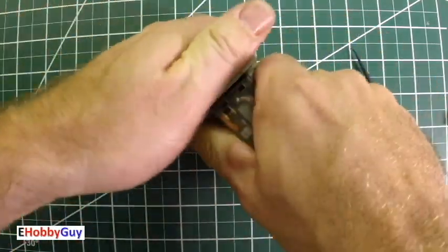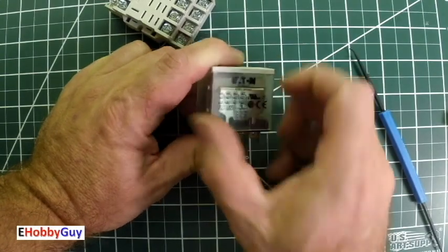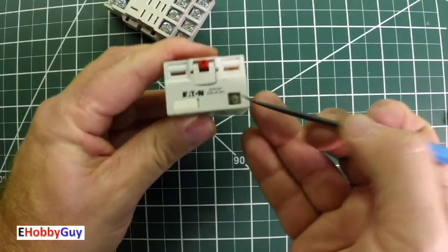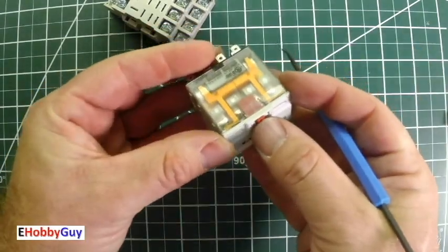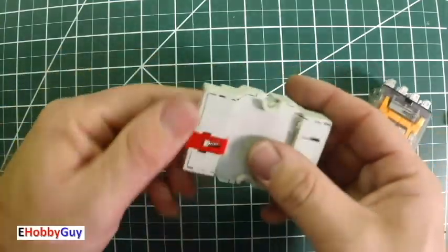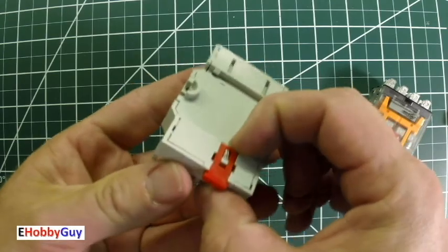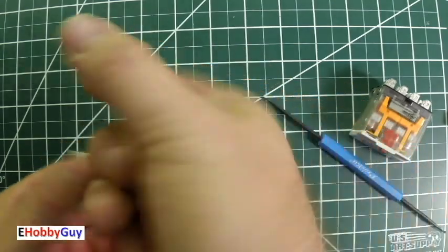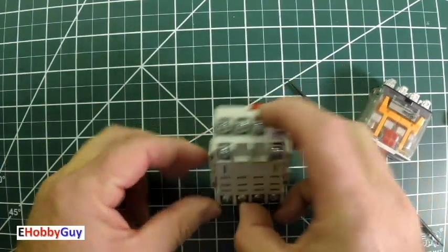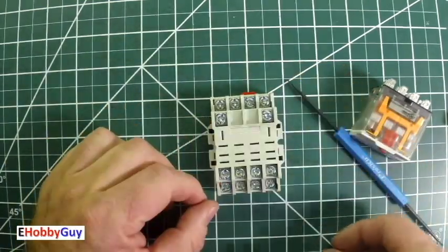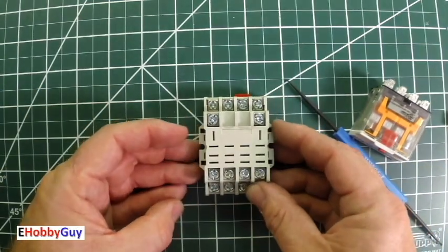It comes with a base, and it shows you which one is normally open, which one's common, and which one's normally closed. Many of these larger relays come with an LED to show when it is active. Looking really quickly at this base, this is actually a DIN mount base, and a DIN rail is like a channel that you would hook and snap onto, and you could mount a rack of them side by side.